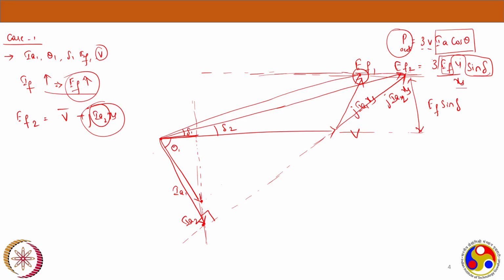If IF increases, my IA2 increases and the IA2 axis drop will increase, and then I have seen my EF2 resultant. So we are coming from the back side, because I know first my EF has increased. For that EF, I have calculated the IA axis drop, and the projection should be IA1, IA2. So now I have got all the equations.